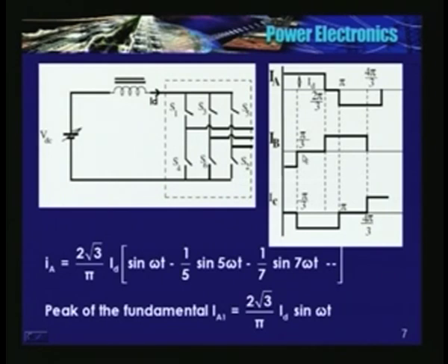See, at this point S6 turned off. In the upper half, S1 is on. So one device has to turn on in the lower half. S4 cannot, because S4 turns on at pi. So at this point S2 turned on.